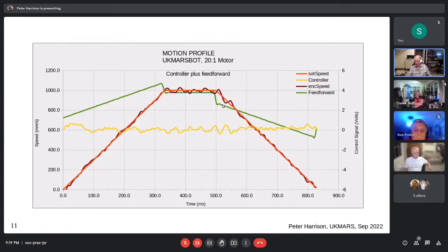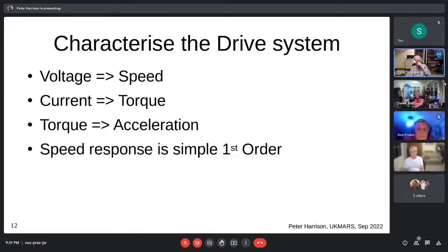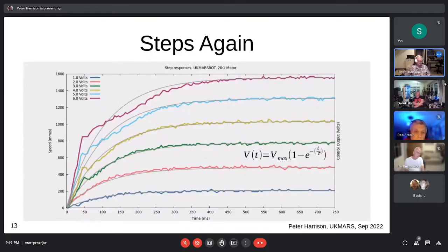And you might reasonably then ask, well, that's all very well, but how do you know how big that step should be? Well, it's actually easier than you might think. Look at this again and consider what's going on at time 0. Down here, the motor's accelerating. And the faster we want it to go in the end, the harder it has to accelerate to get there. Yeah? So the slope of this curve at time 0 is the acceleration, right? Because acceleration is just the derivative of speed against time.